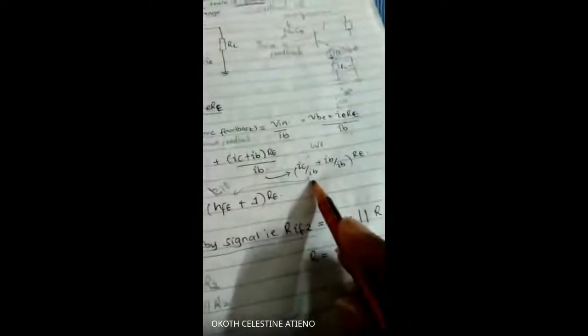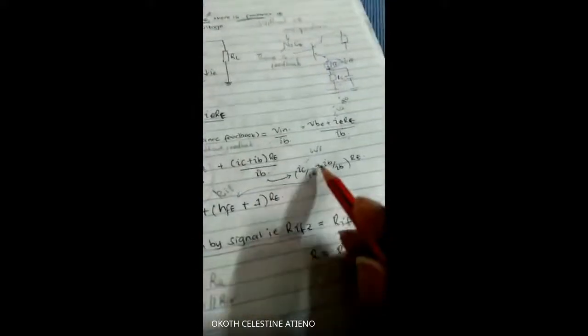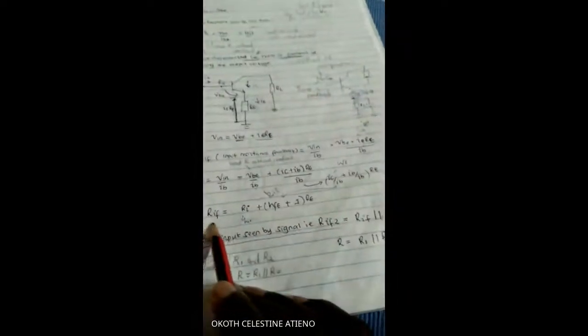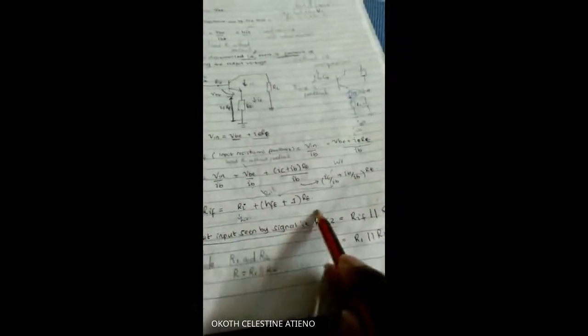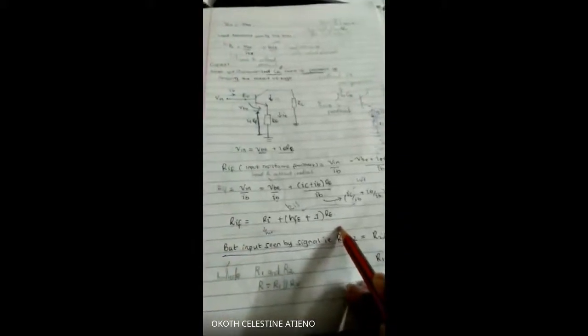Then we have IC over IB. So this expression is basically IC over IB is beta. And you know beta is HFE. IB over IB is 1, RE. So do you guys have any queries or concerns up to here? Because this is what you'll be using to calculate your input resistance with feedback. So kuna mtu akielewa?